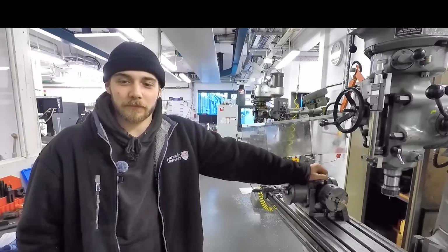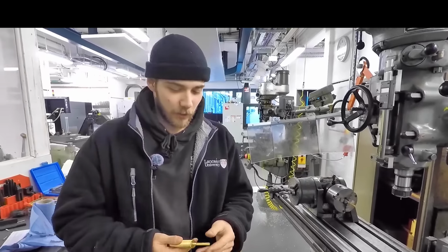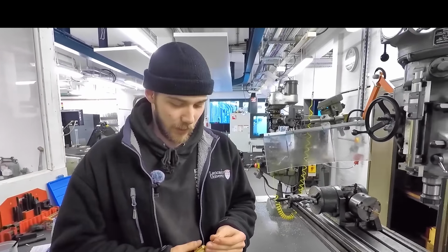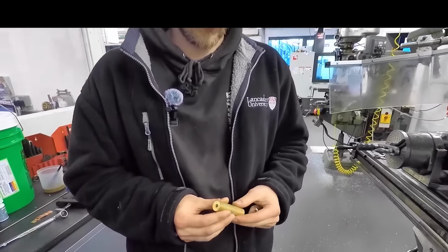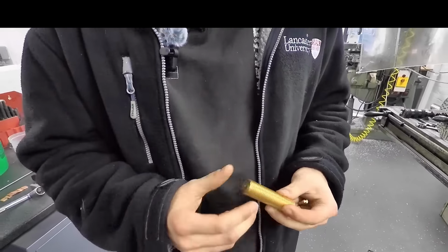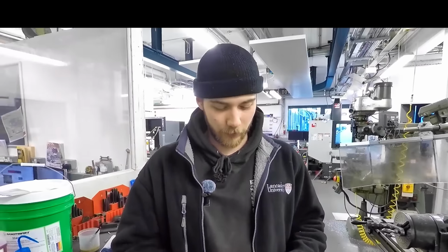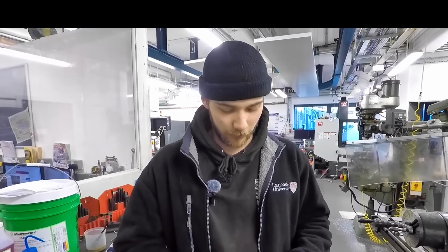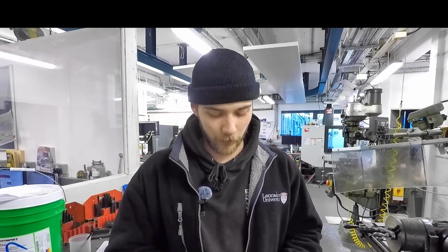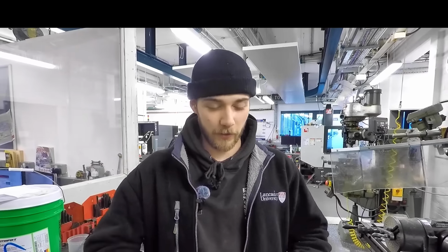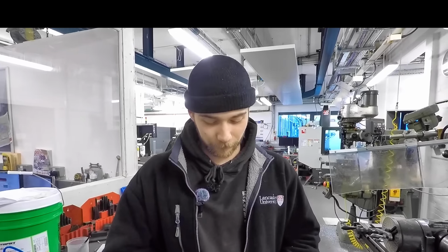And then you bored out the centre of this one. Yeah, so on the other part, we mounted it in a lathe and drilled out the centre, and using a tap just ran it the full way down. But it goes quite deep inside, so I had to grind the tap down so it was the same width the whole way so it could get the extra length, because normally it wouldn't have gotten the correct depth, and to buy a tap in would have been quite expensive because it probably would have been a custom tool. So I just took it to a bench grinder and ground it down so it fit right. That's why you need experts in universities to do this kind of job, because nothing's ever